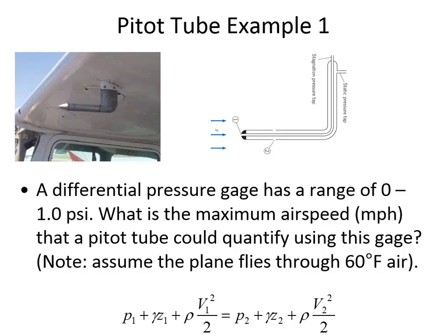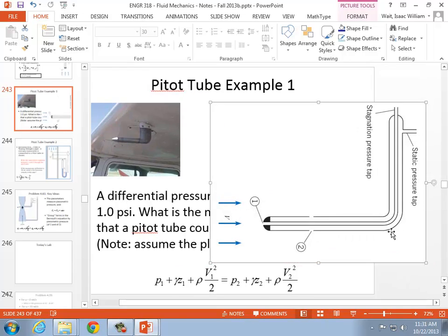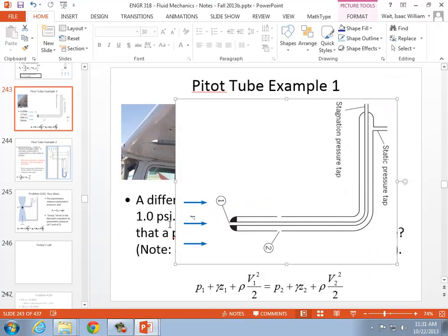Remember that it only goes in at first. On an ongoing steady state basis, the air actually isn't going into the pitot tube, but rather it's causing a pressurization of the pitot tube, because it wants to go in but can't because conditions in there are static. If we zoom in on that diagram, the wind is going through and it wants to go in that little tube, but that little tube at the end of it is connected to a pressure gauge that isn't allowing air to flow through it.